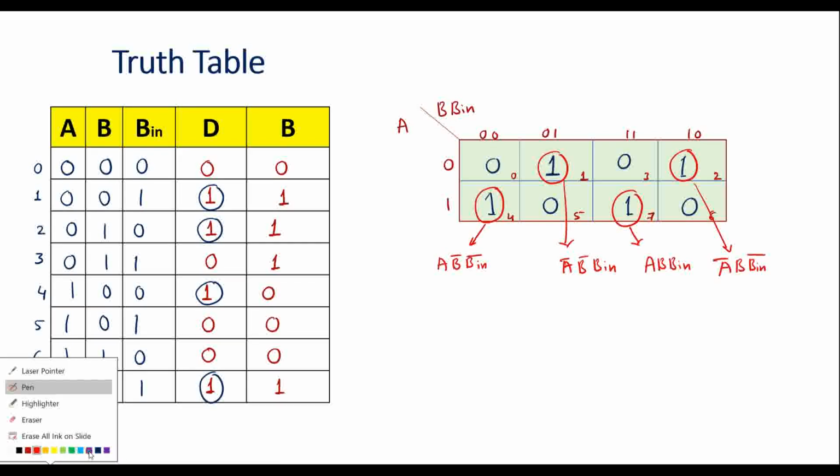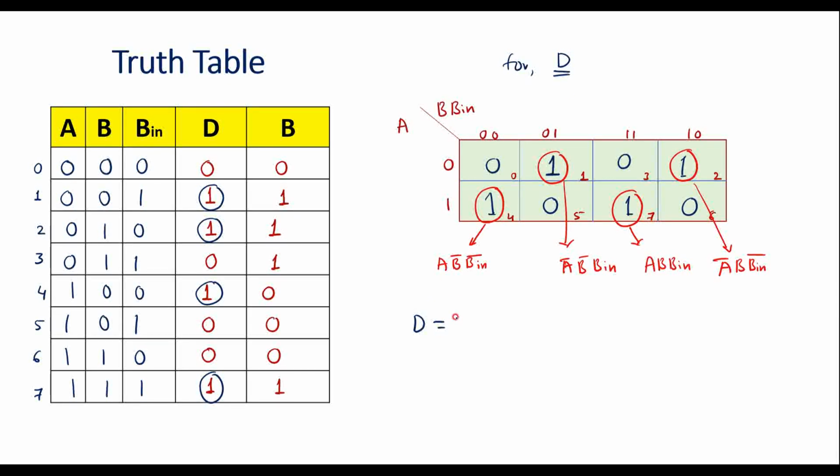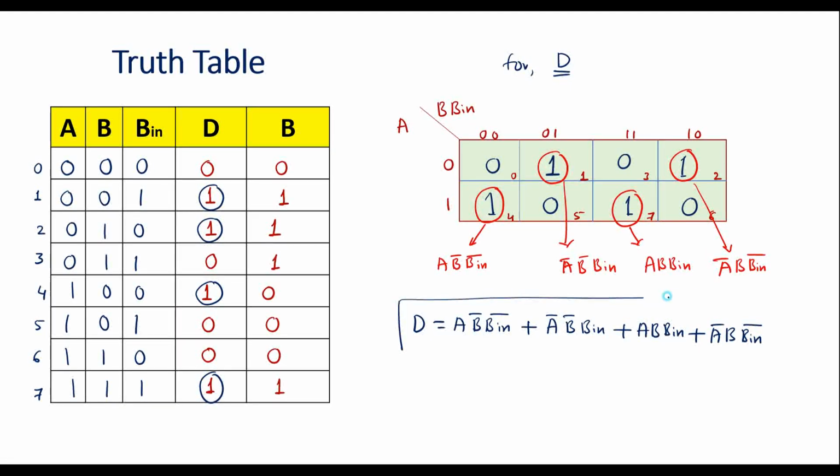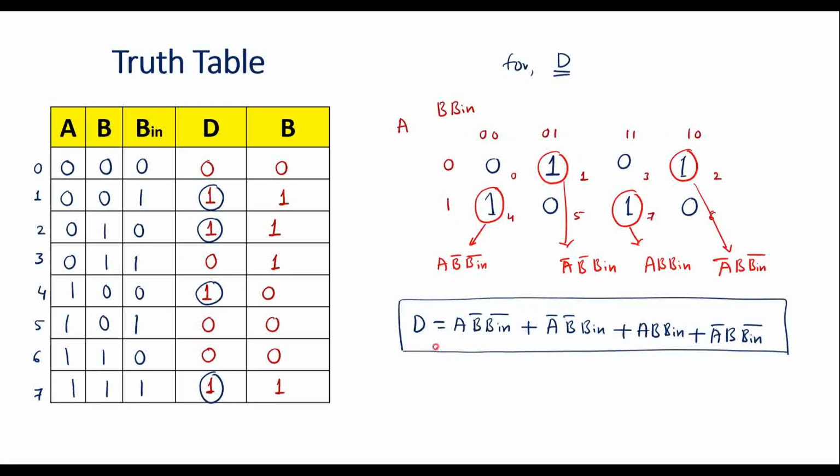Therefore I can write the equation for difference: D equals A B bar B in bar plus A bar B bar B in plus A B B in plus A bar B B in bar. This is the difference equation of the full subtractor.